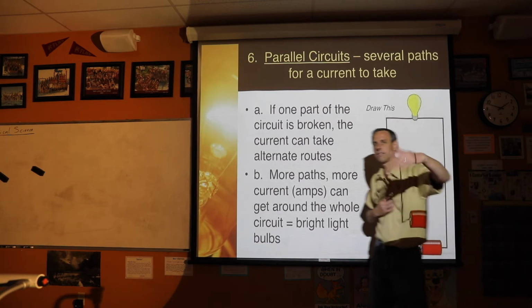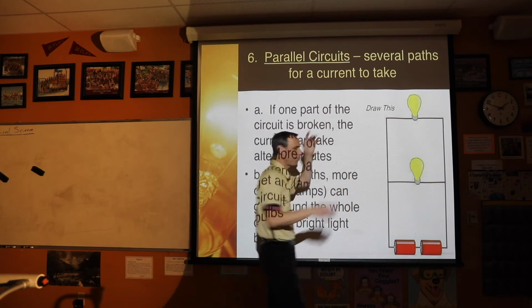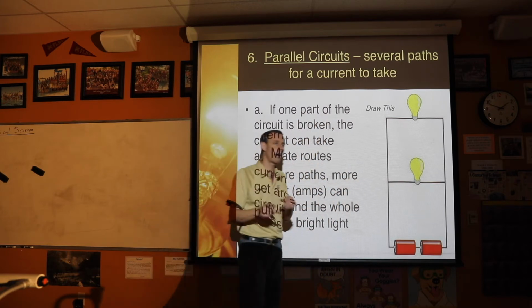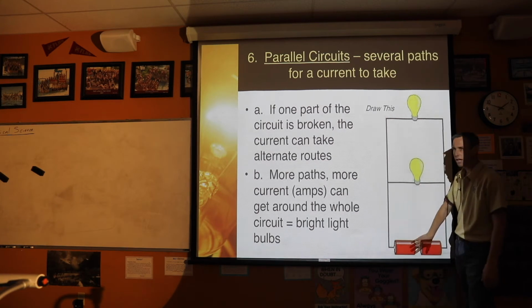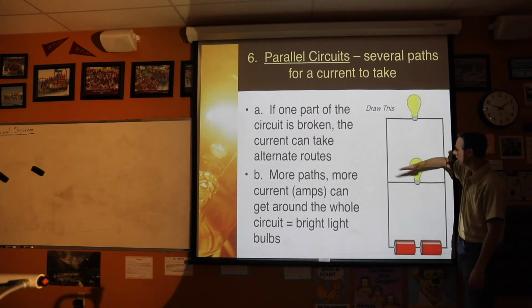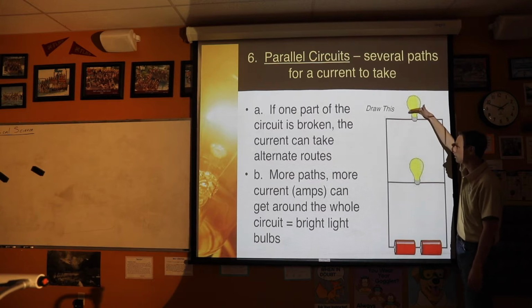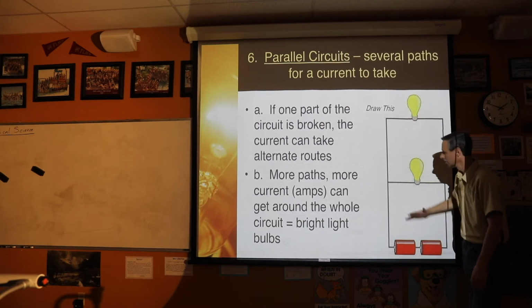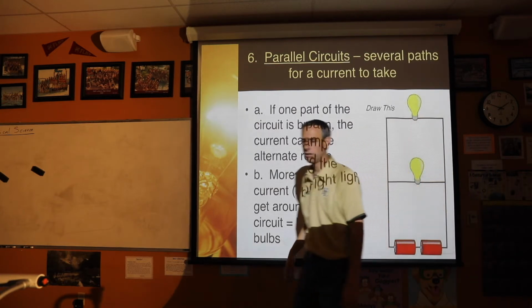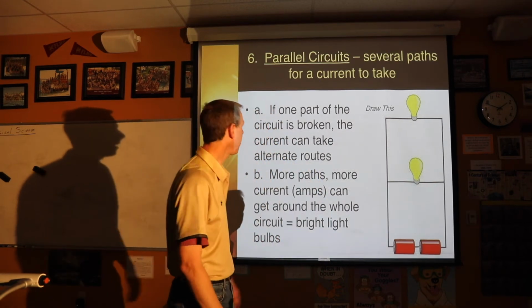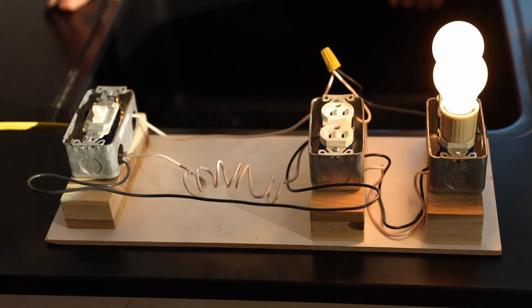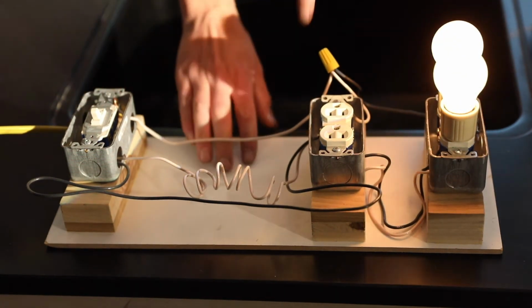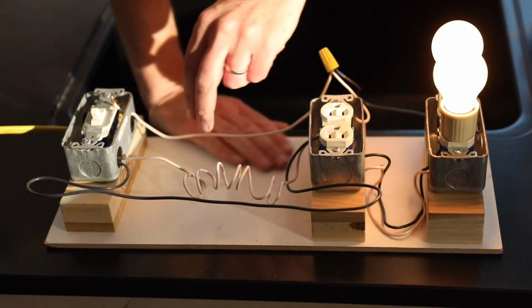In reality, wires are bendy all over the place and making all funny shapes. But when you draw it out, you just draw a ladder, you put your voltage source down here, and then you just start putting pieces across, your appliances across. All right. Now the nice thing about parallel, well, let's show you actually. All right, remember these light bulbs? Now, let's put it into the parallel one. Same light bulbs.